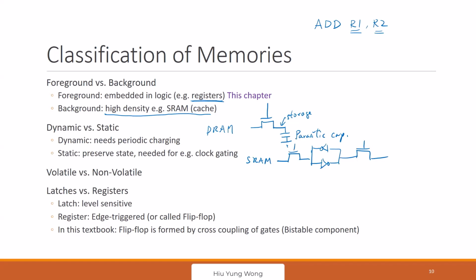I won't go into detail, but you can see if this is 0, this has to be 1. They are bistable, right? Once I store left as 0, then I store the information. I don't need to refresh them because they keep regenerating. Of course, I need to turn on the power supply, VDD, right? So that is the difference between dynamic and static.